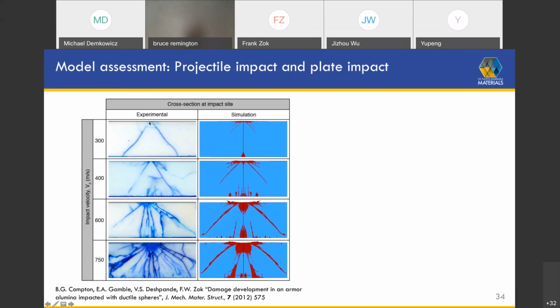There is another aspect to it, which involves the radial cracking, which emerges from the back face. So you can again use a quasi-static solution to work out the hoop stresses that are present on the back face when you've got a rigid foundation subject to a point load up here. And again, if you know the elastic plastic response of the projectile, the size of the projectile, and of course the impact velocity, you can work out what the maximum force is going to be, and in turn, what the maximum hoop stress would be on the back face.